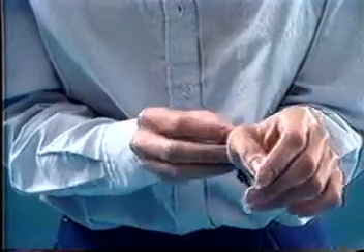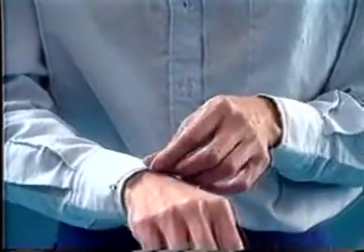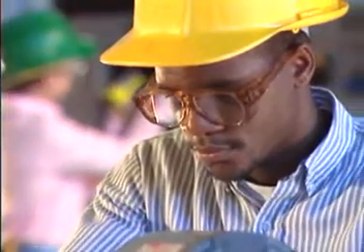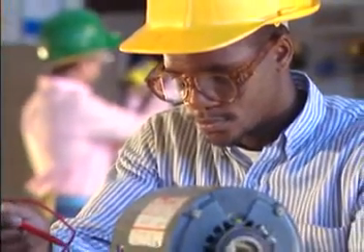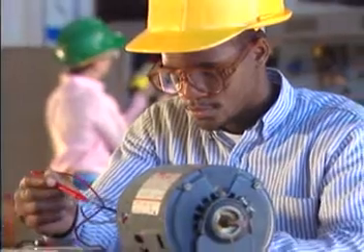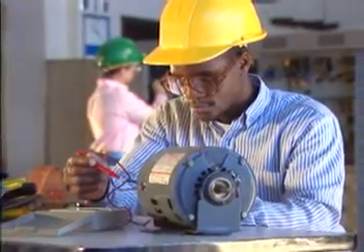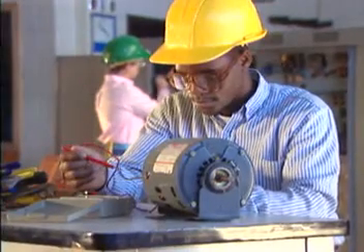Never wear jewelry or any sort of metal when working near electric current. Always wear some form of eye protection. There is no special clothing requirement for electronics technicians other than common sense. No loose clothing that can get caught in the moving parts of an electromechanical device, for example.